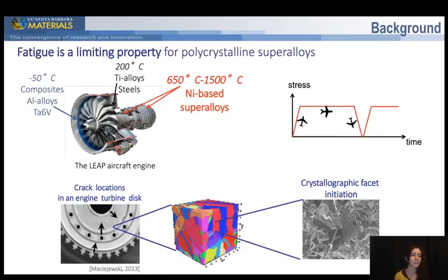Today, we'll focus on alloys for structural applications, and in particular nickel-based superalloys, which are used in jet engines. While single-crystal nickel-based superalloys are quite famous and used for the blades, there are also polycrystalline alloys in these engines, which are used for the discs on which the blades are mounted. During service, these parts are subjected to rather harsh thermomechanical solicitations, namely fatigue and creep fatigue, at temperatures in the range of 650 degrees C.